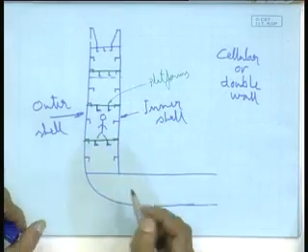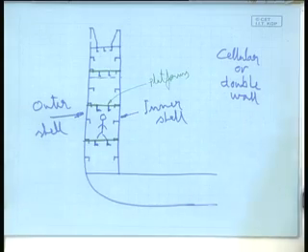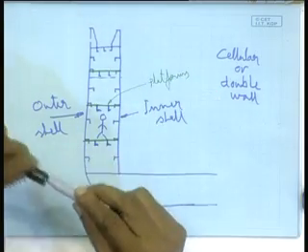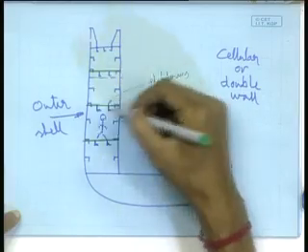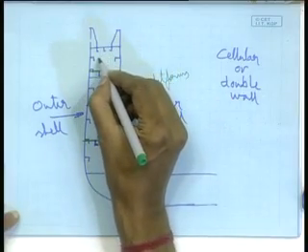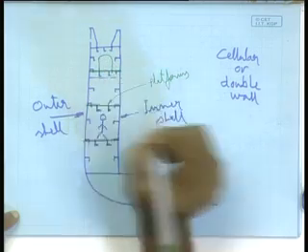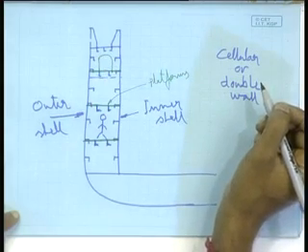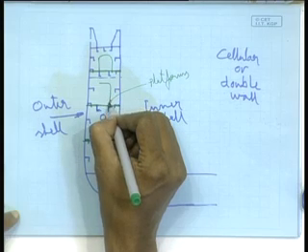So, this is what a double wall construction is. Now, we see that it is perfectly done as far as longitudinal strength is concerned, and to provide for the required transverse strength, and also providing for supports to the longitudinals, you now have similar types of transverses. Right.